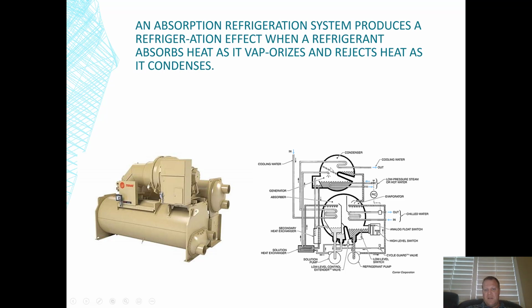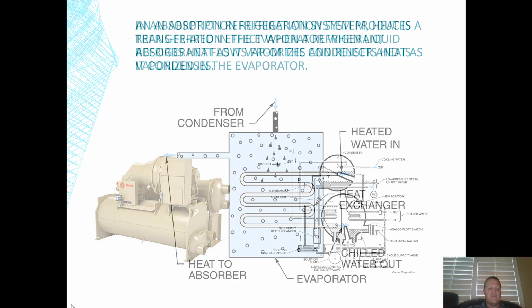But imagine one section being a condenser, the other section being the compressor, and the idea here is that it's the same cycle as refrigerant, but we're not using air. We're using liquid. We're creating chilled water out of this side, and we need to waste our heat out of that side. So go all the way back. Let's go back.